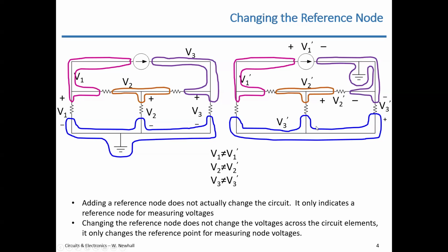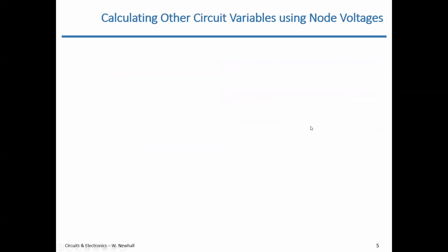All right. One important thing about node voltages is this: once you've used node voltage analysis, which we will get to, to calculate all the node voltages in a circuit, you are only one or two steps away from solving for all the other circuit variables, all the other currents, all the other powers in the circuit. So that's what's nice about having a methodical way of solving for node voltages: then you can go one more step and calculate currents, calculate powers. It's really easy from there.